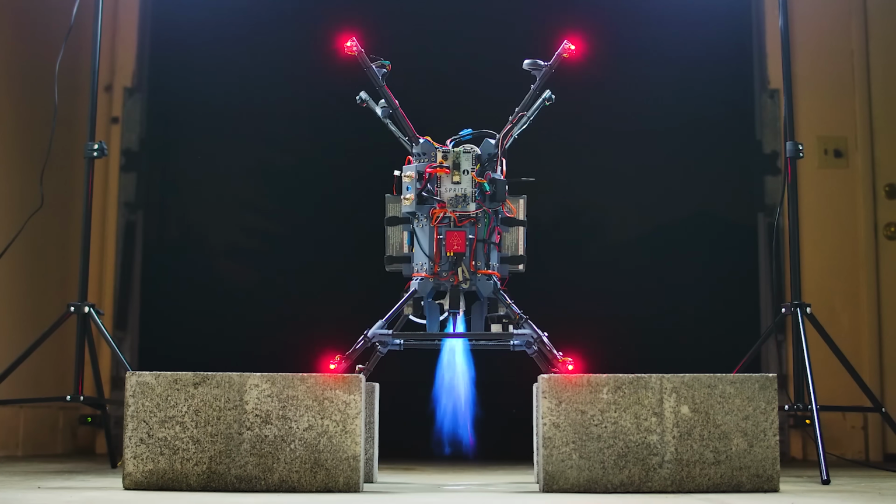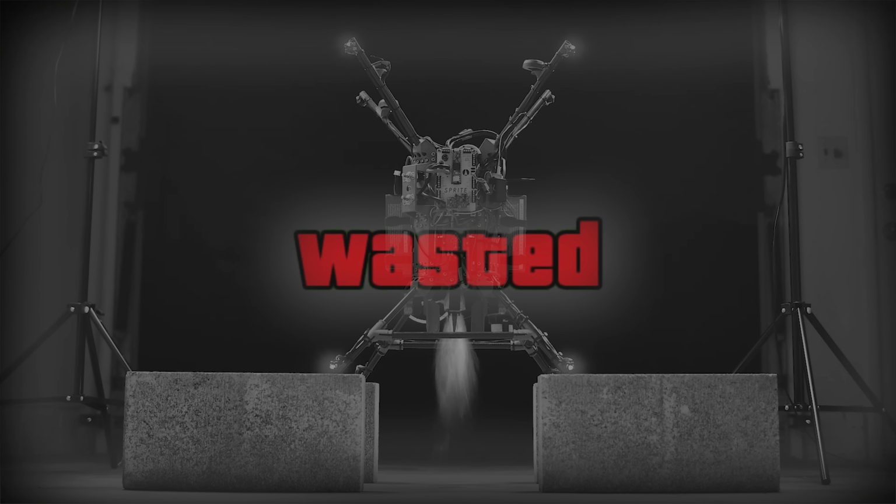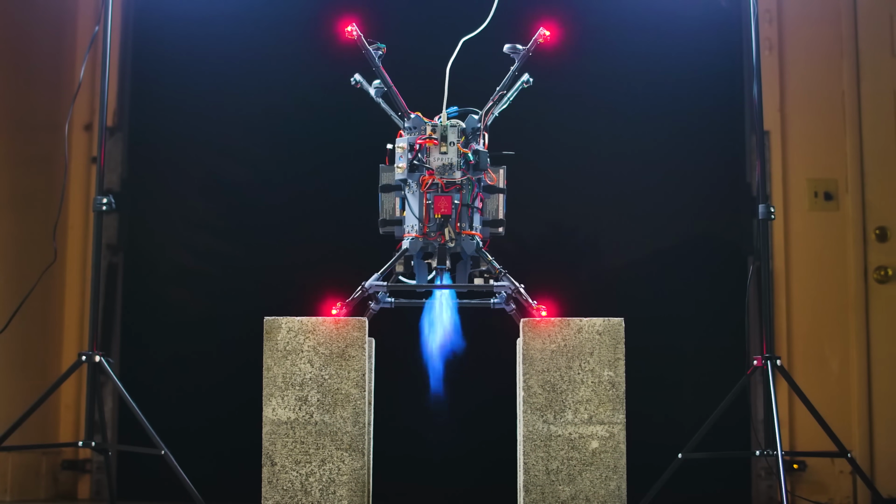The next thing on the list of updates is Sprite's afterburner, which is unfortunately gone. Even after lots of iteration and a bunch of modifications, a bunch of testing, and like 2 or 3 weeks of cumulative work, I could not get the flame to stay lit or combustion to continue past 40% throttle on the fan. Now, here's the thing, there are totally ways to make this work, and I'm sure that with enough time and enough testing, I could get the afterburner to hold a flame at 100% throttle and do what we needed it to do.